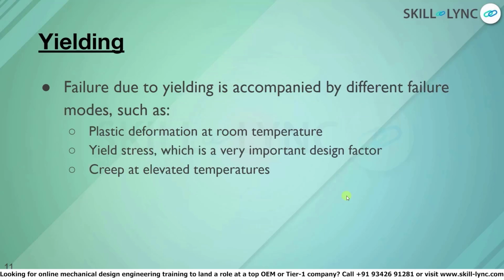The next common type of failure is yielding failure. Failure due to yielding can again be accompanied by three different modes. One is plastic deformation at room temperature. The second one is yield stress, which is a very important design factor. The third one is creep at elevated temperatures.